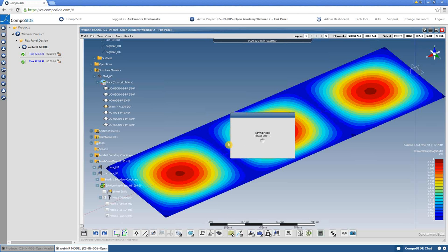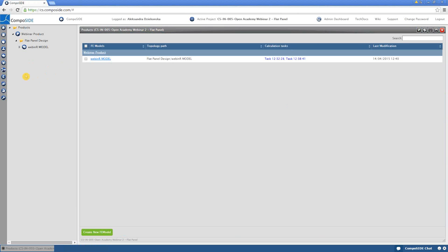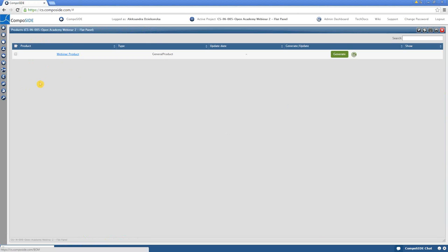And we will quickly move to the BOM-Gen tool. One thing worth mentioning, the BOM will be derived based on the mesh of the FE model, so make sure it's the right mesh you want a bill of material of. Having said that, you can always manually change your areas and quantities within the BOM, so it's not limited in this case. Again, if some units will be taken from your subscription, we always will tell you that.